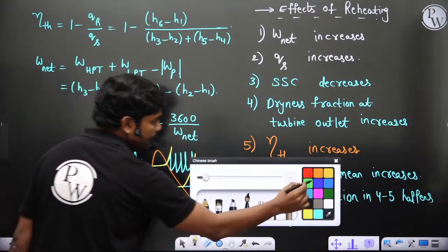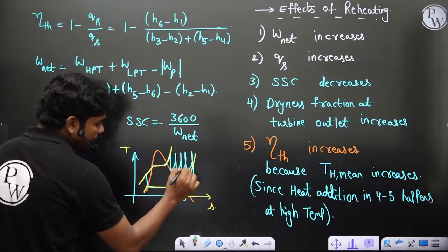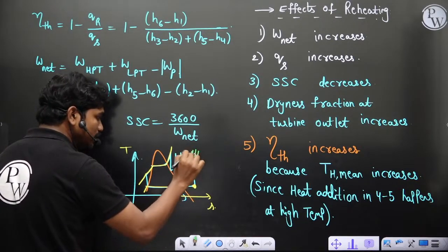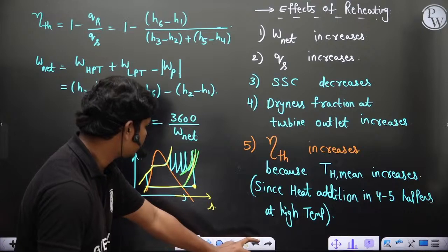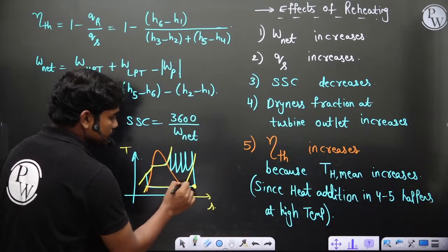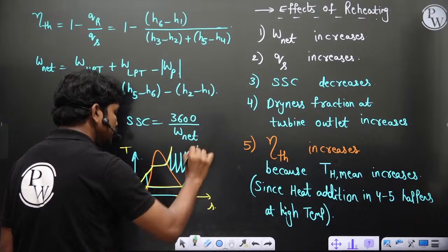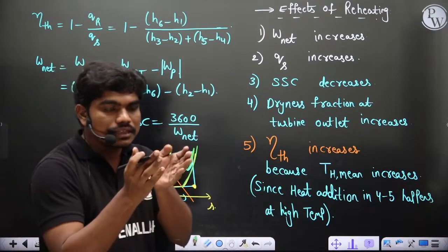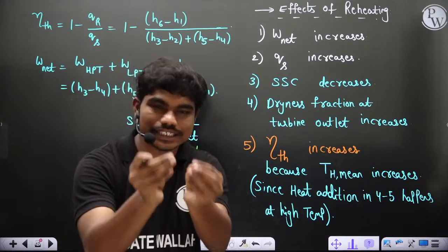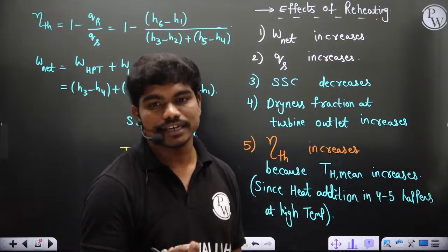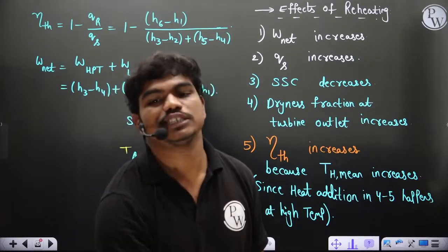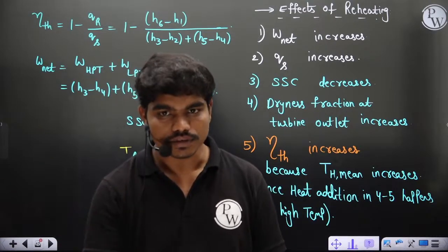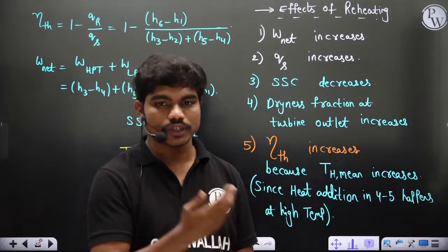You can understand, as you go forward, this pressure line and the pressure line at which you are reheating, these two lines becomes very close to each other. Understood? I'm just repeating. See here, if this is the actual pressure line at which you are, for example, doing this, and if you take this line of reheating, these two lines will be very much close to each other. That means the pressure difference across the turbine is very small. Okay, so that means power generated by the turbine because of that excess reheating is much small. Understood? So practically that will not serve the purpose of putting a turbine. Okay, so it's not at all economical, so that's why they won't do that.